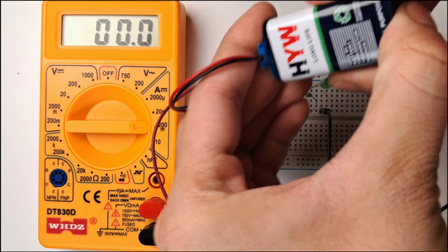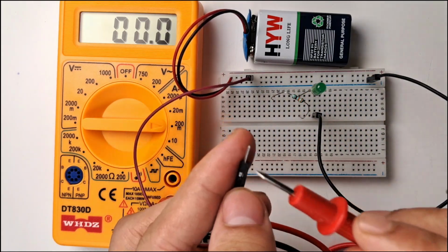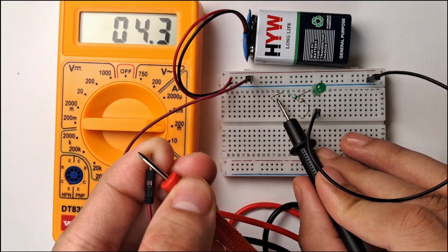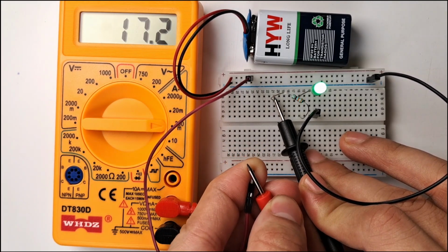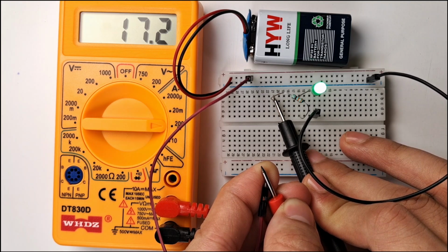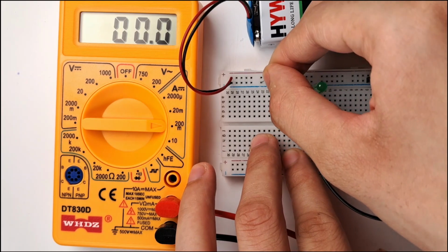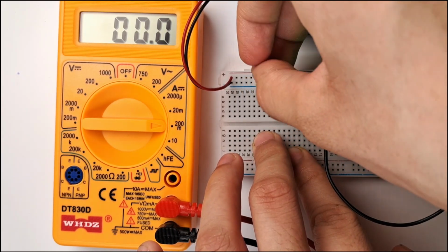Now connect the battery in the battery connector. Now we have to connect the red probe of the multimeter with this jumper wire which is connected with the positive supply of the battery and connect the black probe with this resistor. Now we can see that the LED is taking around 17.2 milliampere of current. So this way we can measure our electric current. Now make the connection as the initial circuit. This is the initial circuit which we have made.